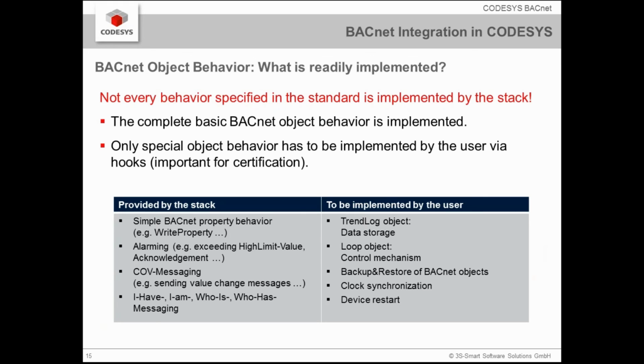Regarding BACnet object behavior, what is readily implemented in our product or within the stack? So therefore, it's important to say not every behavior specified in the BACnet standard is implemented by the stack. What is implemented is the complete basic BACnet object behavior, and only special object behavior has to be implemented by the user. So what does that mean?